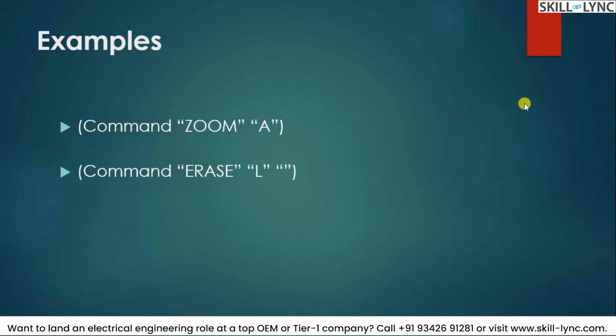So likewise, if you want to erase all this, then once the command erase is invoked, the next sequence we give is the character L, and in order to execute it, that is after selecting the objects, you then have to press enter to close this erase command.